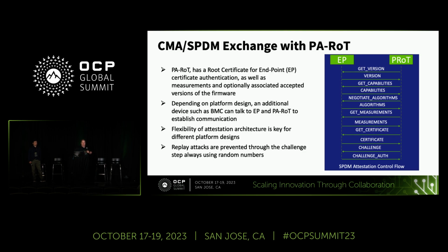Then the measurements are requested. It also provides the certificate back. And this last stage here, we'll talk about it in a second, it's very important, the challenge. Because if you read through this on the right, it really reads that I could just do a replay attack on this. If I'm listening to the bus, I could just say that these are the same things coming back if I've augmented the firmware. But that challenge right there requires that something be signed and sent back. So if you have modified maliciously the firmware, it can't be replayed. It's different every single time.